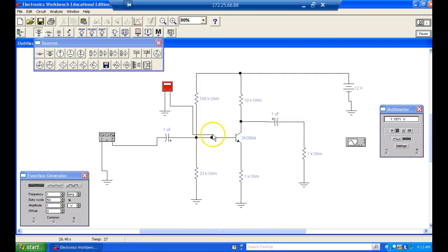We want 2.3 volts drop right there. Because what we want is 600 microamps over here, right? All right. Oh, we want 2.3 right here, so you're right. So we end up with what right there? 1.3. Okay, that's not too bad then.